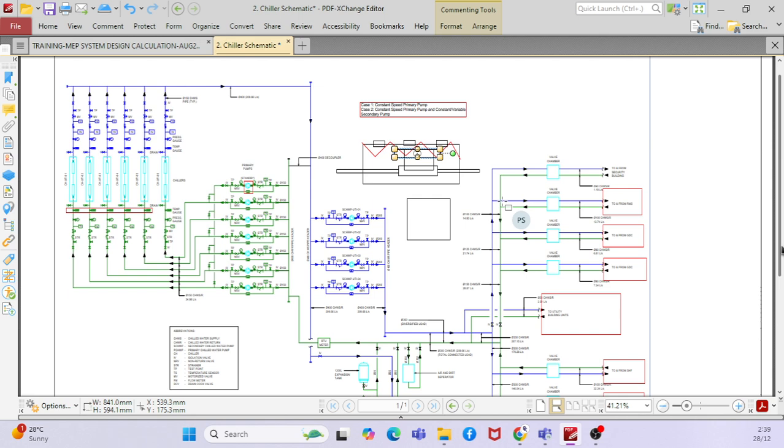Yes. Clear, right? Okay. So what will happen when a lesser flow comes into the chiller, right? Yeah, it will come to the return line. When there is a lesser flow, it will check whether the first chiller is pumping 50 liters per second, the second is pumping 50, the third is pumping 50, but the fourth doesn't have enough water, right?